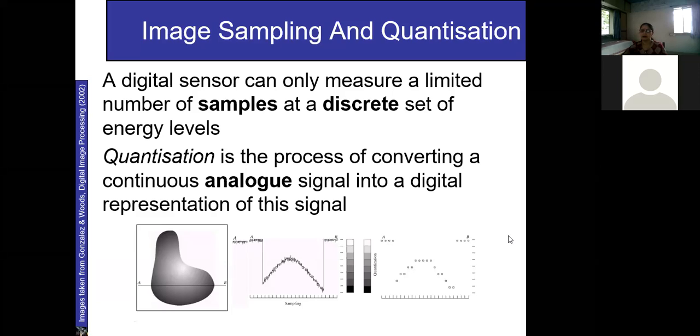Okay, in the chat box there is a question: what is the need to discretize an image? When we discretize an image, basically we get digital data. After discretization, it is possible to represent it in digital format, and once we represent it in digital format, only then can we apply various algorithms on that image. So the main intention in converting your analog signal into a digital or discrete signal is making the next processing of images very simple.